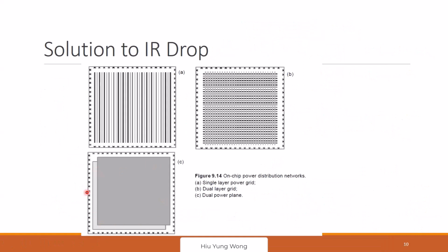That is great, right? What are the drawbacks for all of this? Nothing is free. Each of these power lines needs a pin. Pins are very expensive. You have limited pins. Second, they're going to create a lot of capacitance, right? So you need your pins, and then parasitic capacitance is going to increase. You need to be very careful. Okay.